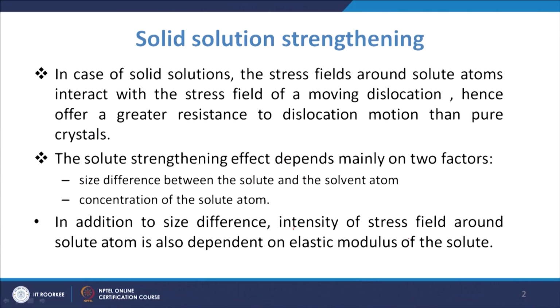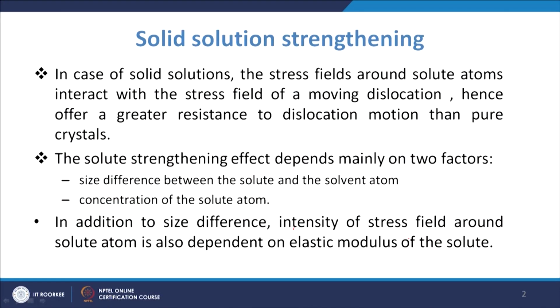So when we talk about solute strengthening, the effect depends mainly on two factors. One is the size difference between the solute atom and the solvent atom, and that will affect the strengthening effect. The second is the concentration of the solute atom. These two factors are important.